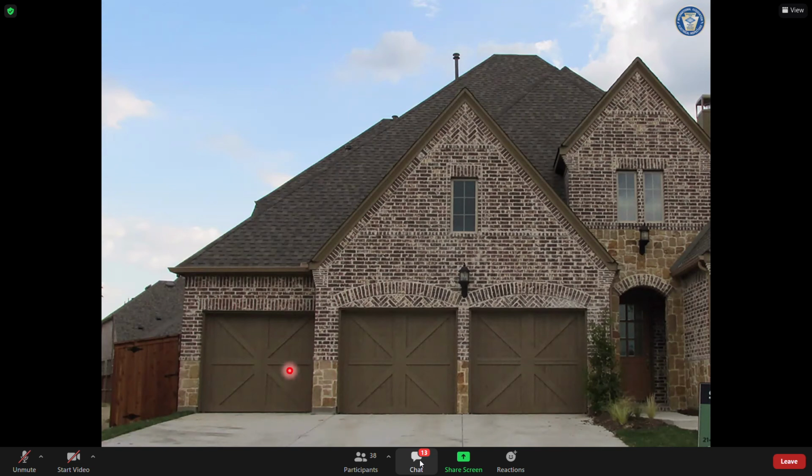2011 NEC, 2012 IRC, one receptacle somewhere in this garage. 2014 NEC, 2015 IRC, I propose I could put one receptacle right here and one receptacle right there, and that receptacle could be for that car space and that car space. So I'm up to 2 receptacles.